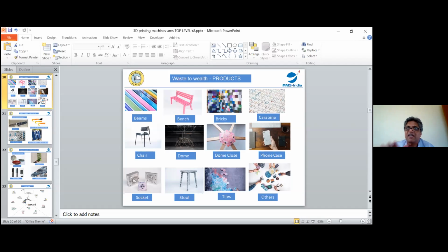The press machine basically has a top and bottom heater, and you make one small hexagon shape. You'll have one MS hexagon shape welded and kept. That may cost you only about 500 rupees, for example. Then you put all the powder inside this and heat it on top and bottom. It will become the shape that you want, like a tile or a stool or everything.